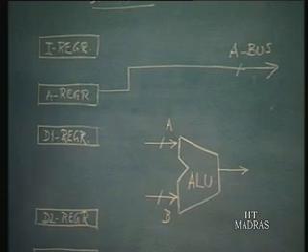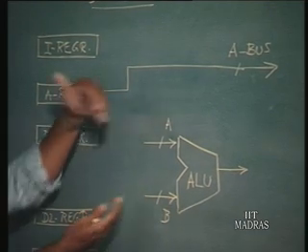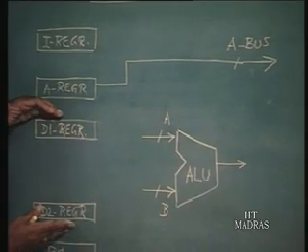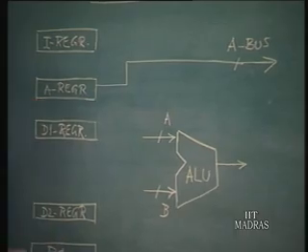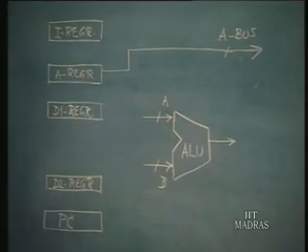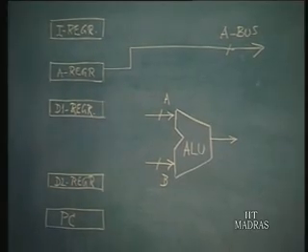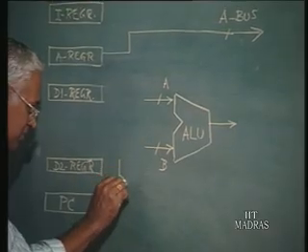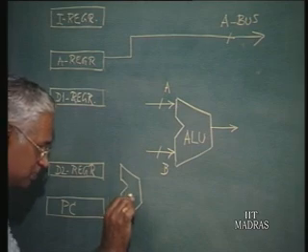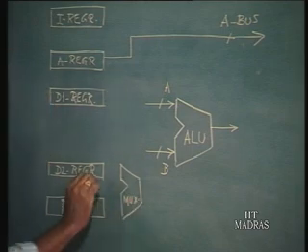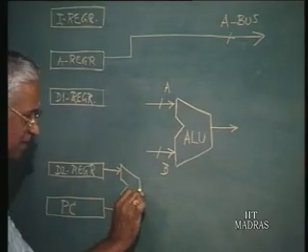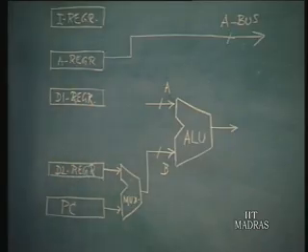Okay. Now, the ALU will subsequently be involved in carrying out some processing on the two data, but subsequently we have to possibly also pass the program counter contents to the A register. So, the path for that also must be created. What I would do here is introduce one multiplexer, if necessary we will name it later. So, either the content of this or the program counter content will be passed on to this ALU, right.